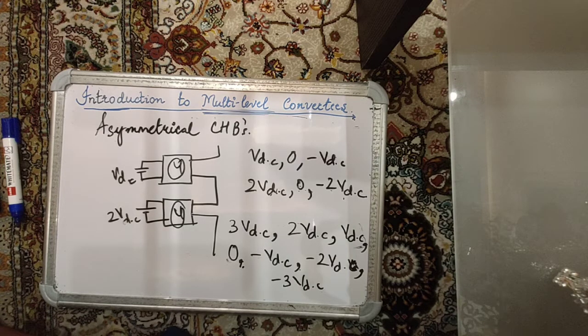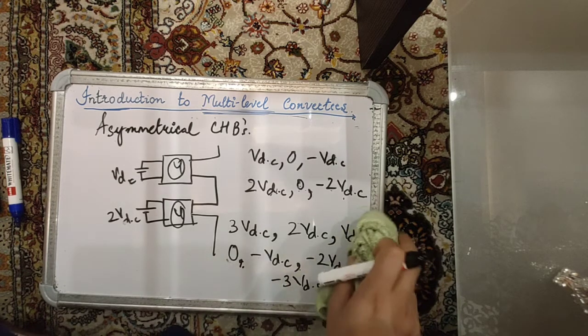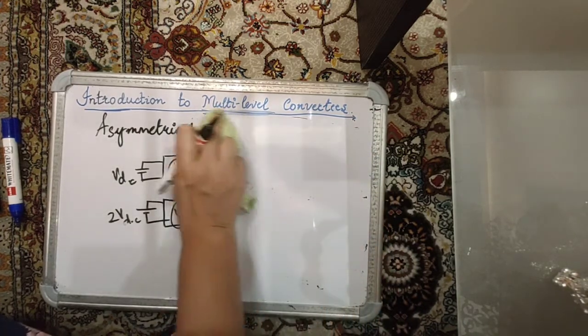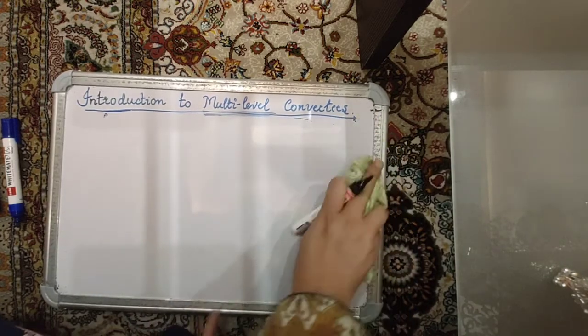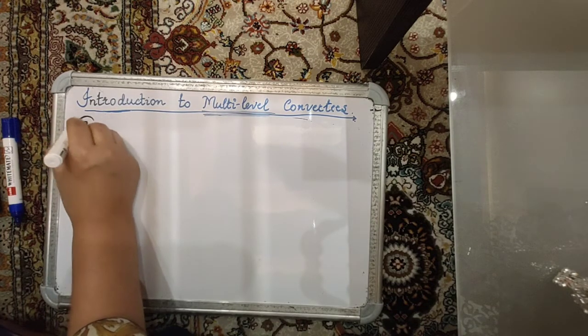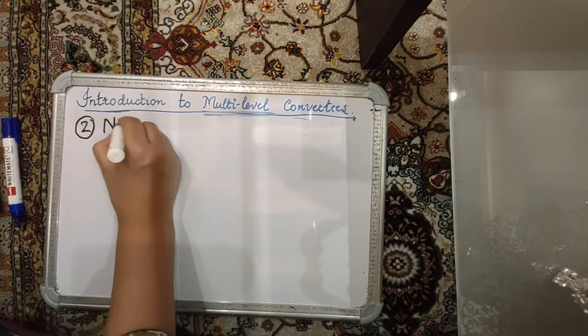I'm sure you have already studied in PWM techniques the level shifted and phase shifted PWM techniques for doing the modulation of these converters. Our basic goal is to move to space vector modulation of multi-level converters, and this is just to introduce you to multi-level converters. Now let's move to the second type of multi-level converters, that is the neutral point clamped converter,